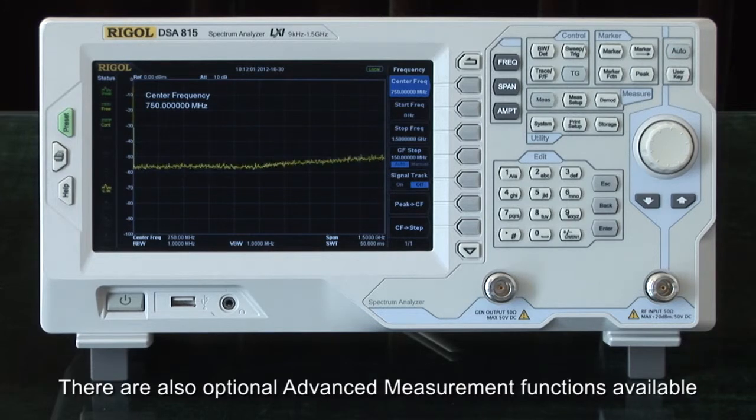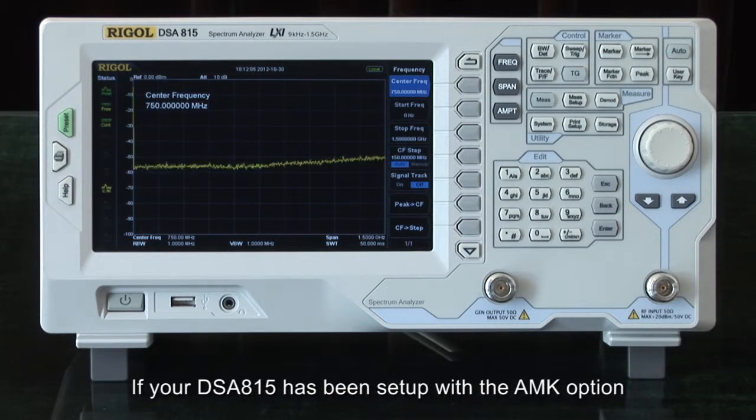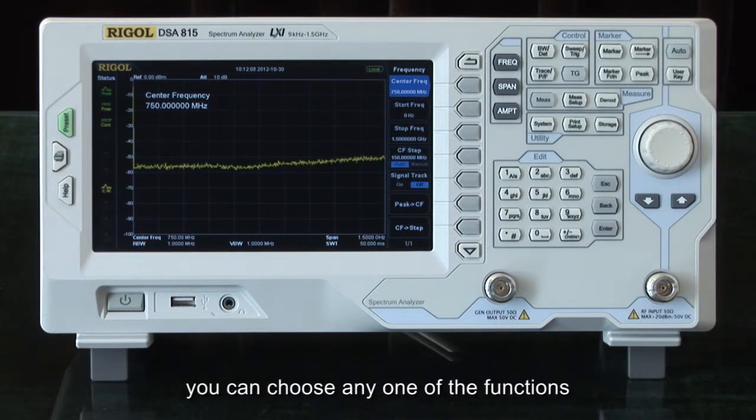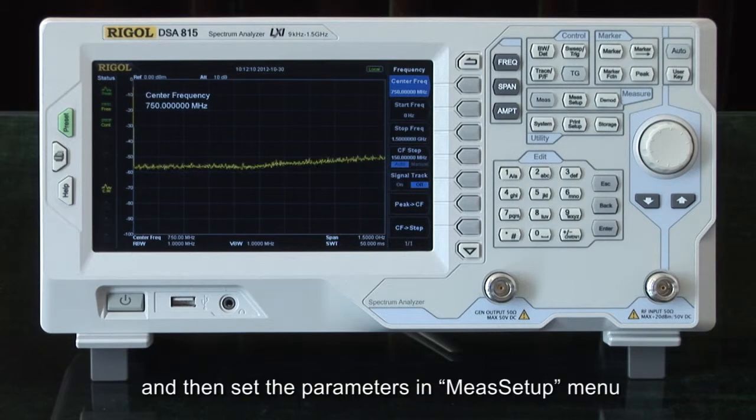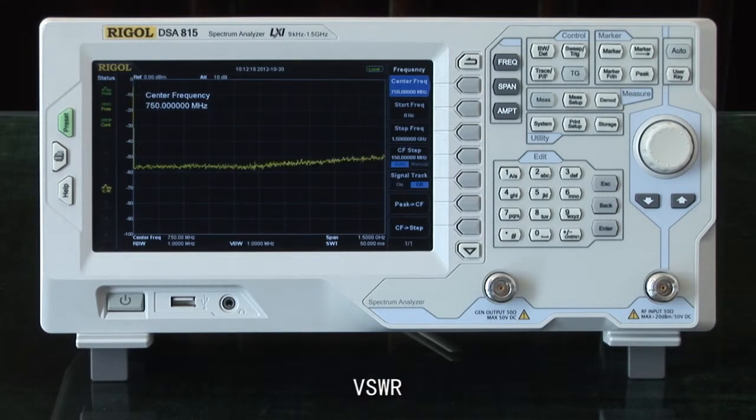There are also optional advanced measurement functions available. If your DSA-815 has been set up with the AMK option, you can choose any of the functions and set the parameters in the Measure Setup menu. Press the Measure button, and we can see the advanced measurement functions: VSWR, total power, adjacent channel power, occupied bandwidth, emission bandwidth, carrier-to-noise ratio, harmonic distortion, and TOI.